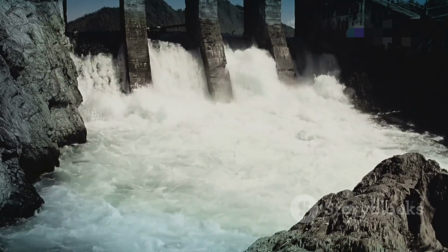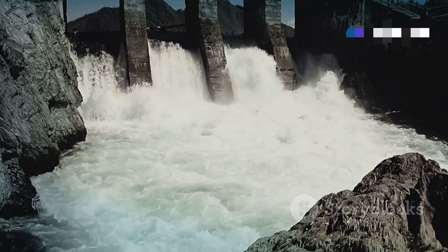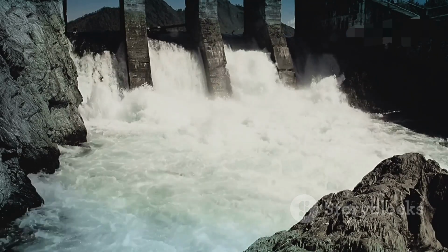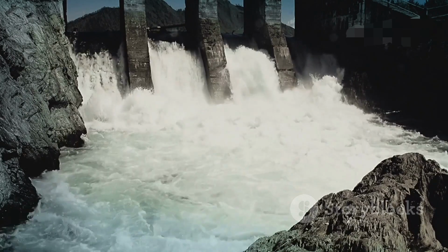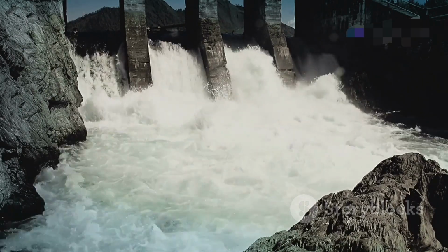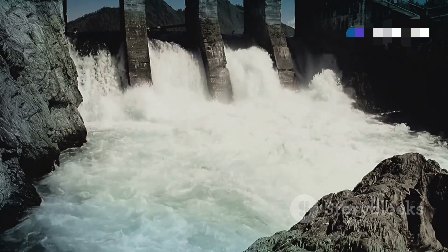Typical values for earthen dam breach side slopes range from nearly vertical, 0H:1V, for very cohesive soils or short development times, to 1 vertical unit to 1 or 2 horizontal units, 1V:1H or 1V:2H, for less cohesive materials. HEC-RAS uses these dimensions to calculate the geometry of the flow area as the breach develops.